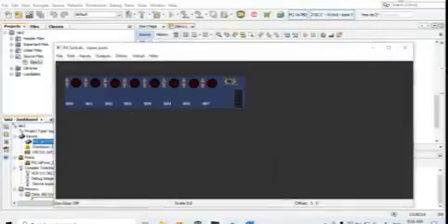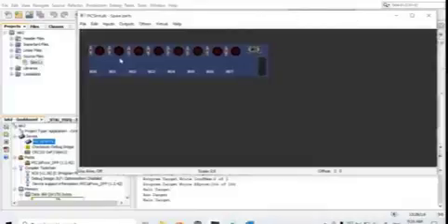Okay, so this is the LED on the PicSim side. So we just connect all the LED to port D. If you want to rename or connect to another port, you need to go to properties. So you can see RD0, RD1, RD2 up to RD7. We want to view all the 8 bits on port D, so we connect all the port D to the LED. So everything is perfectly in order.